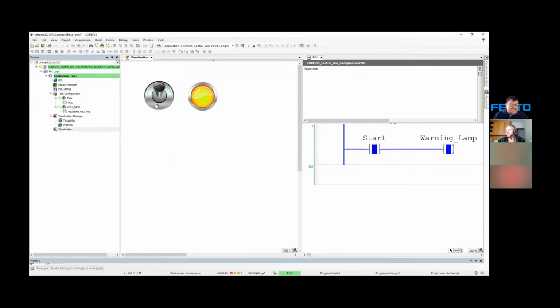Now, this is a basic ladder program, all right? And that means we will take you step by step through everything and explain to you exactly what I said to you previously. What happened is, the moment when you put your PLC in run mode, it scans your PII, writes the result into your PII table, and executes your user program. The result of the program will go to your PIQ, and the PIQ will then send out your result to your physical output. And that's actually a small little ladder program.